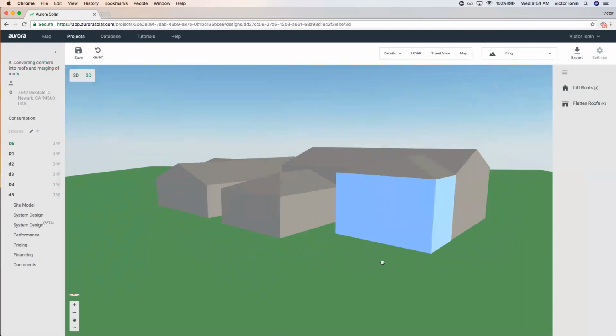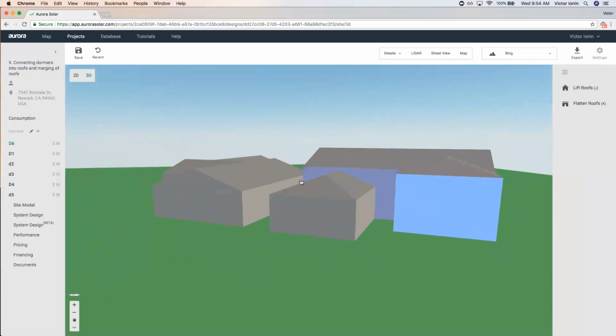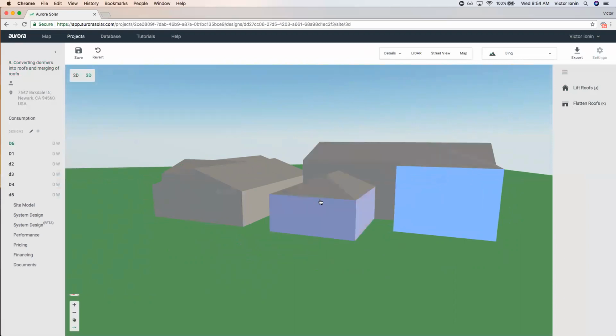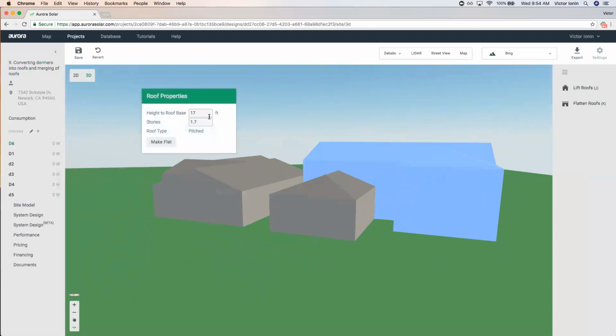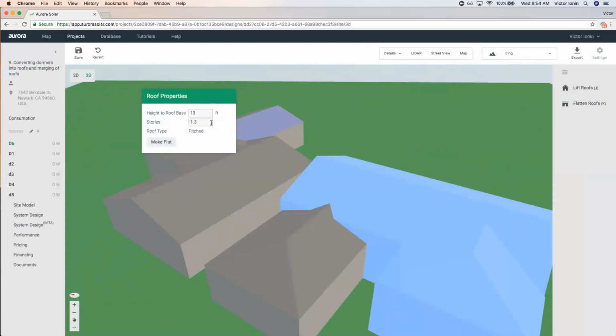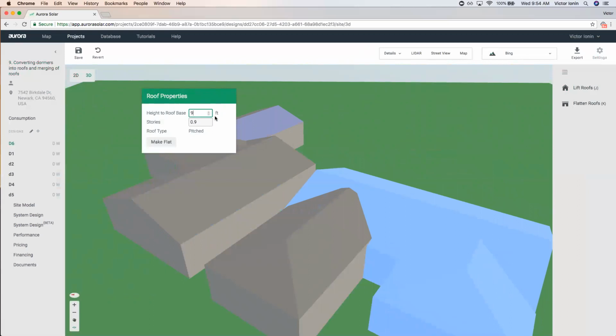And why would you want to do that? Well, in some cases, a roof might look like this, where your garage ridge line doesn't meet the eave of the other structure, right? So there might be a height difference. One section's one story tall, the other section's two story tall. So it gives you more flexibility to adjust. You also notice that the valley lines will automatically get created as you change the height. The software will know where the valleys need to be.